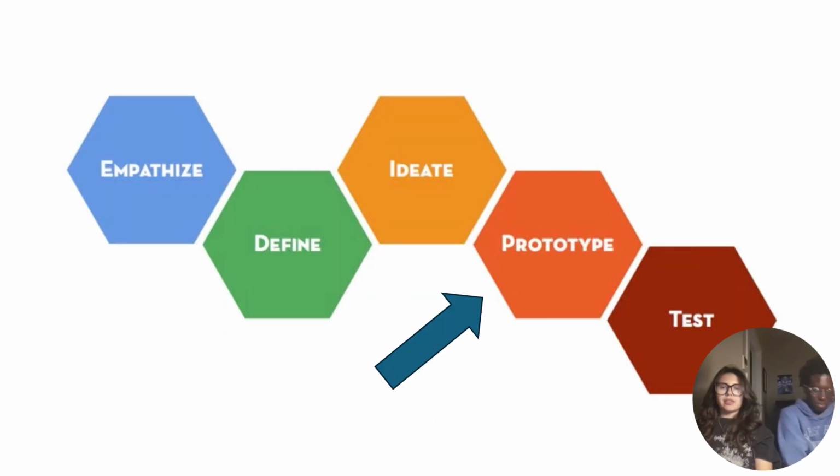After figuring out that a heel activated pedal was the best concept and the most natural motion, we have then moved from the ideate process to now the prototyping. We began developing the physical mechanism itself. Initially, we wanted to use springs to maintain the pressure application of the pedal towards the piezoelectric discs.